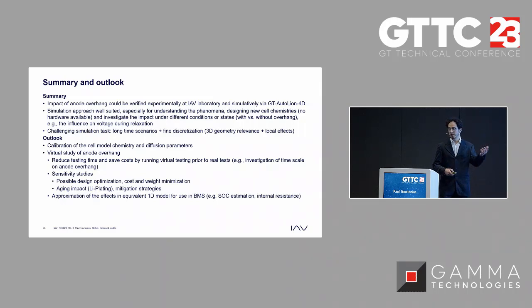I said at the beginning, the anode overhang is linked to the lithium plating topic and aging. So once the environment is set up, we can then also look at that. And we can also imagine to derive some simplified models, maybe 1D or similar, to integrate in the BMS to account for that.